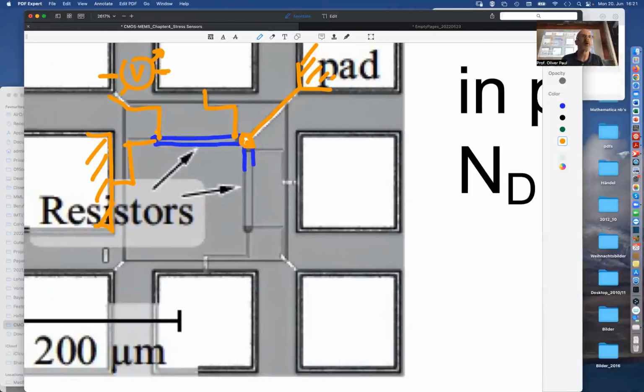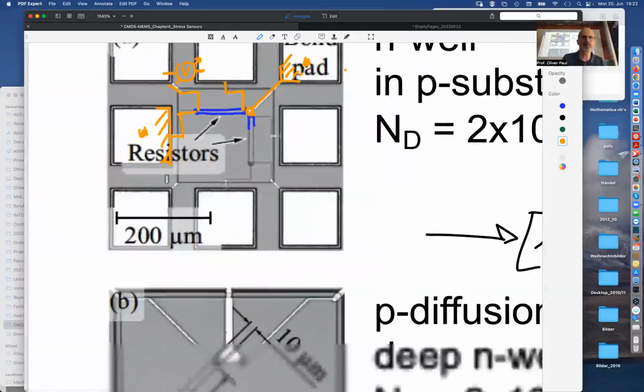This is very important, because you could also take the resistance measurement from here to here. You also get a value, but then you have a resistance value of blue plus some yellow plus some contact resistance between the two materials, and you get some approximation again. But we would like to do some real material science in such a measurement, and that's why utmost care is taken.